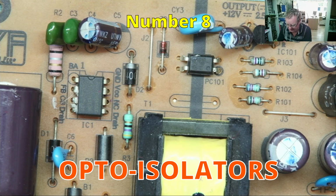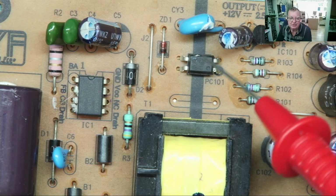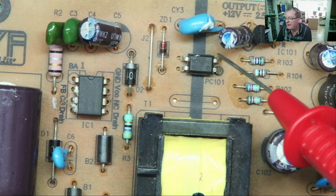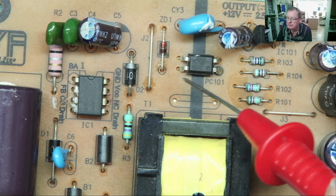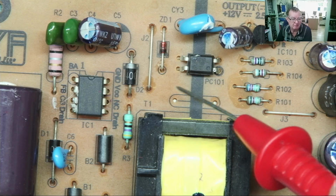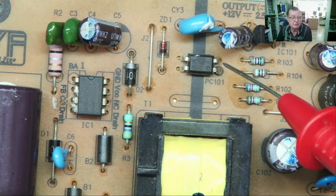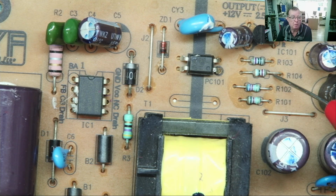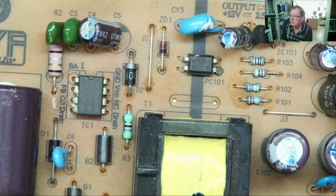And number 8 is opto isolators. Inside the opto isolator or opto coupler, we have on one side an LED, an infrared LED, and on the other side a phototransistor, or maybe a photothyristor or phototriac, something like that. And the way this basically works: if you want to send a signal from one part of the circuit to the other, whilst maintaining electrical isolation, so there's no electrical connection between the two sides, one way to do that is with an opto coupler.